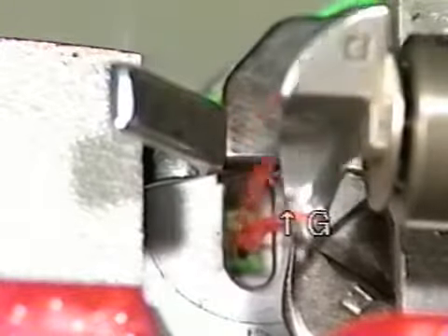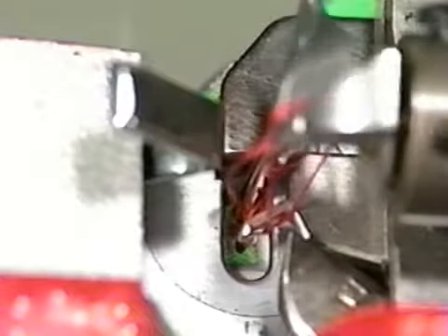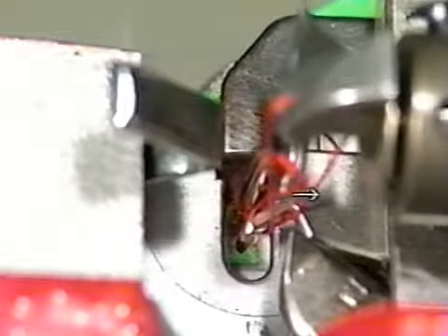The yoke slide moves backward when the machine sews the 8th or 9th stitch. At this time, the looper point should pass the center of thread triangle G. In addition, adjust the triangular cam and the yoke slide cam so that the yoke slide moves backward immediately after the looper point has passed the thread triangle.